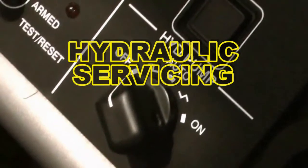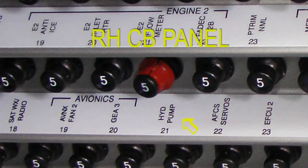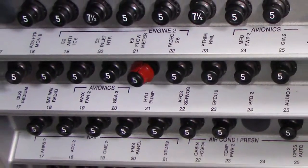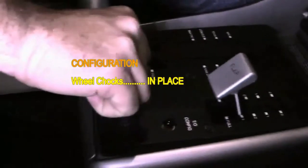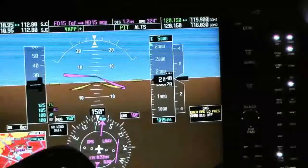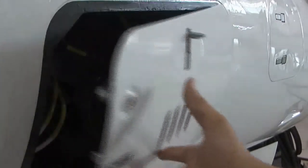Hydraulic servicing. Turn off the hydraulic pumps. Open the circuit breaker hydraulic pump and put a circuit breaker ring and tag on it. Dump the emergency parking brake accumulator by cycling the emergency parking brake handle until the indicating light on the main panel goes off. Open the hydraulic power pack unit access door.